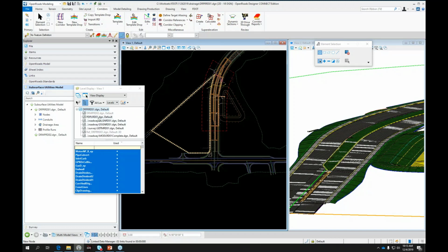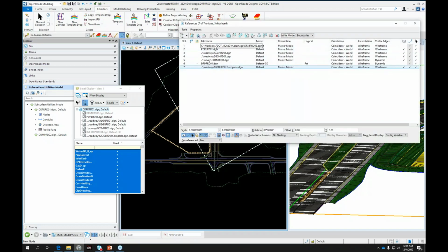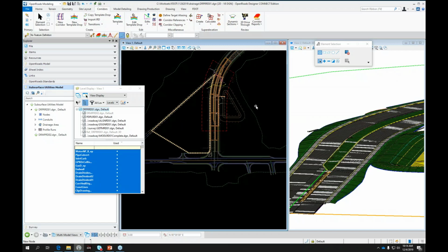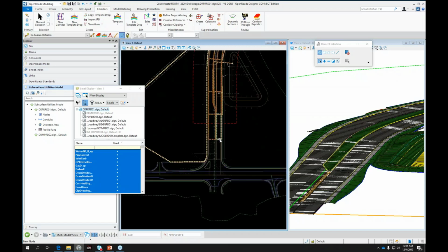So the other thing is, I mentioned that in the plan, I actually have a referenced drainage map that has my drainage boundaries. It's recommended that you lay those out in a cell when you go to define your catchments. You can copy in those drainage areas, and then it's going to change them into a feature. That's just so if anything happens, you'll still have your drainage delineation boundaries, because it actually rewrites them into a feature once they're in the file. So you can lay them out with MicroStation or any other tool for laying them out. But once you make them a catchment feature, it's going to change the status of them. So we recommend making a backup of that.